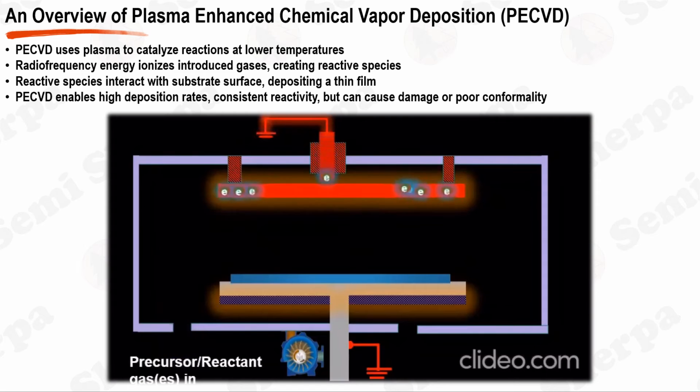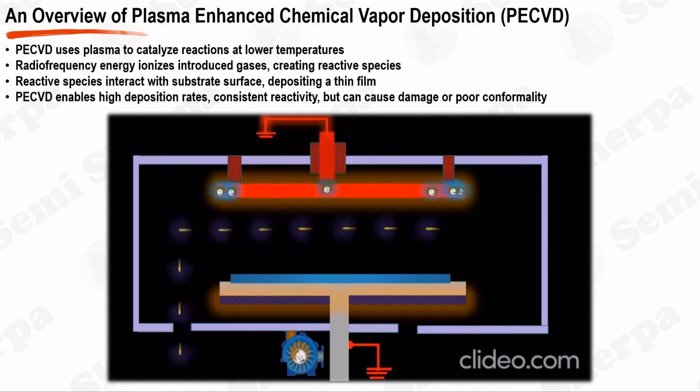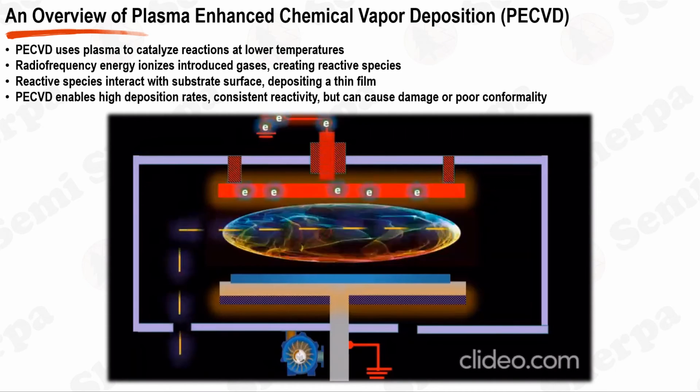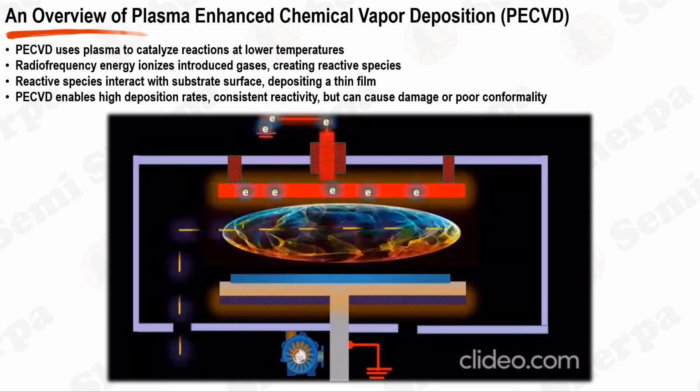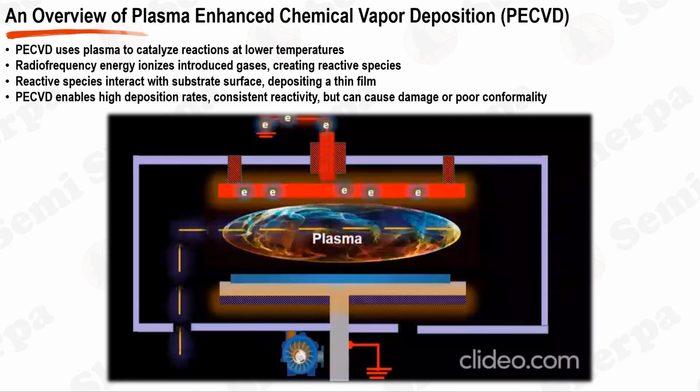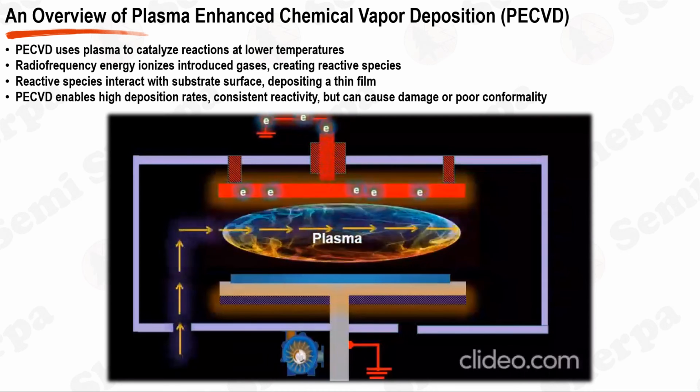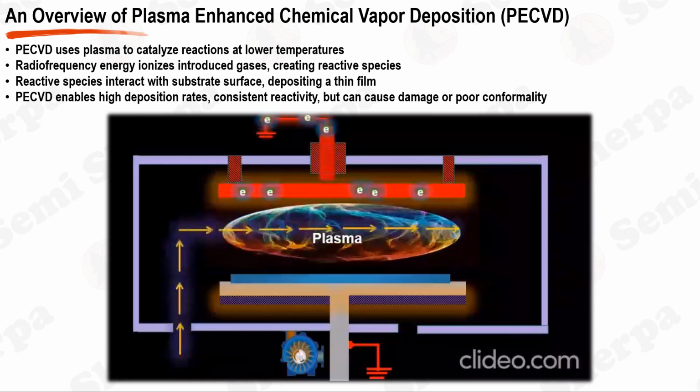Nevertheless, PECVD is not without its drawbacks. The reduced process temperature can hinder the removal of byproducts. The ion bombardment inherent in the process could potentially cause damage. The use of reactive species can lead to homogeneous reactions. Finally, the step coverage can be poor, displaying a PVD-like process, although this can vary depending on the material.